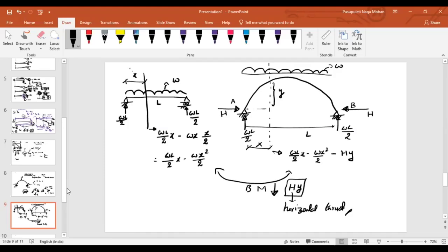I have observed, I have roamed in Tamil Nadu, but in Hyderabad, I can say that there are some spans in the metro. Depending upon the span, they have selected this type of arches. Hollow is one of the options. Hollow sections plus arches, they have combined both. So both will become very, very efficient.